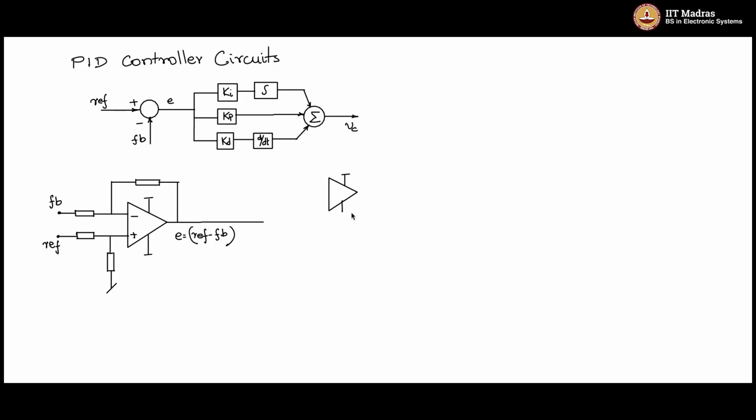So let us mimic that. I'll take one op-amp, VCC, VEE, plus and minus. I will ground this, and I will take, in the inverting amplifier mode, an integrator action. So I'll have a resistor here, and I will have a capacitor here. And this is an integrator.